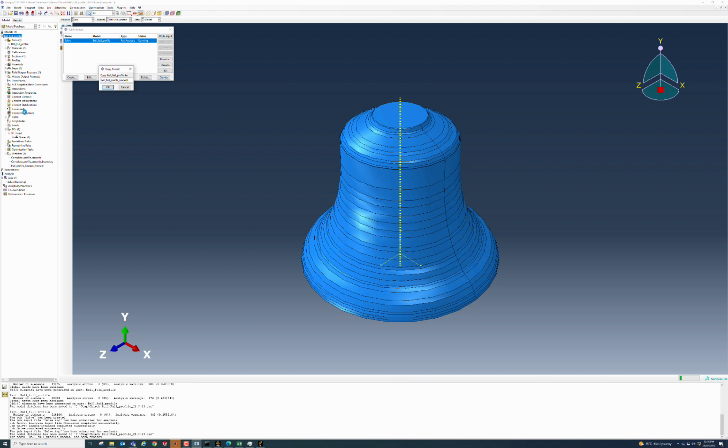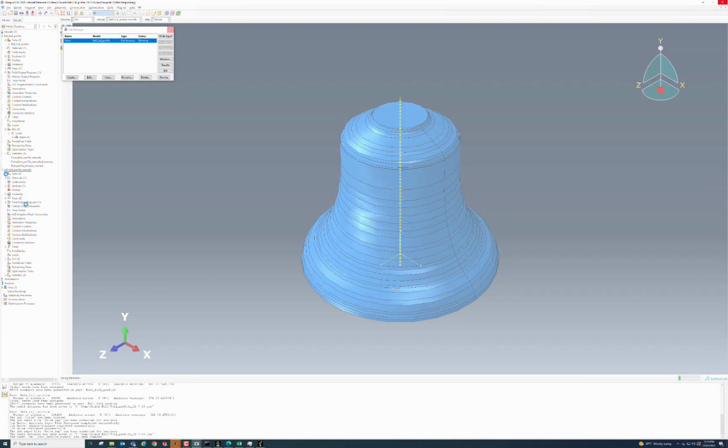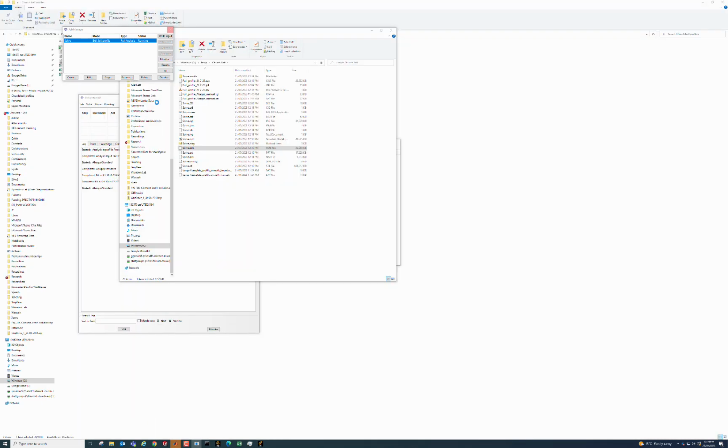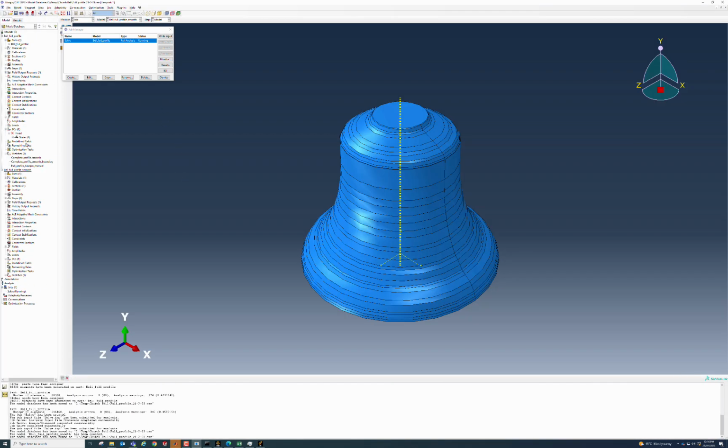And you can see when the new window comes up, it gives me the chance to rename it, so I'll call it smooth, because I'm going to change the profile to make it smoother, so we can eliminate that step problem that we have observed. And now it's open, I can expand it in the model tree, open the part that's also been copied. All of the things that were in the previous model have been copied across, and then I can edit the part to change the profile.